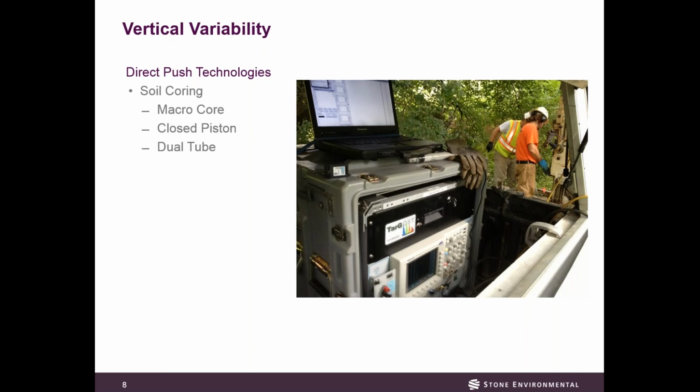But I have a couple of things here. If you're doing a sampling plan, you might have this many jars to fill up, right? So you have your VOC jars. This might be for waste characterization if you're doing something that a landfill or disposal facility needs. So it's an 8-ounce amber jar for the folks on the phone, and then a 4-ounce jar. This is often for metals, PCBs, SVOCs, etc.